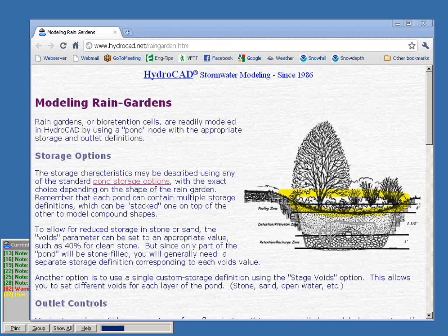this level water surface. And you'll notice, of course, that the rain garden has a lot more complex stuff happening at the lower levels, that we're not necessarily just filled to some level with water. We have a pool of water perhaps at the surface, but then the material below may not be fully saturated. So the overall rain garden does not meet our definition for a pond.